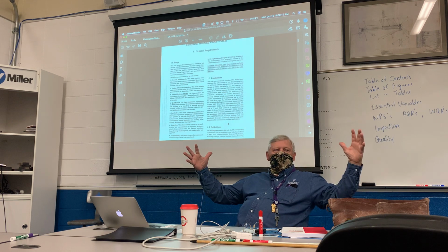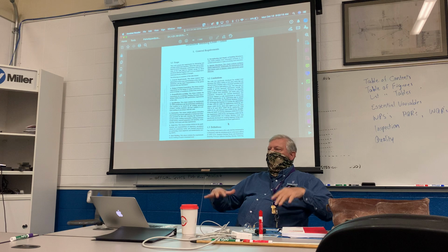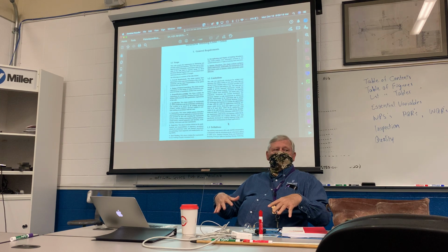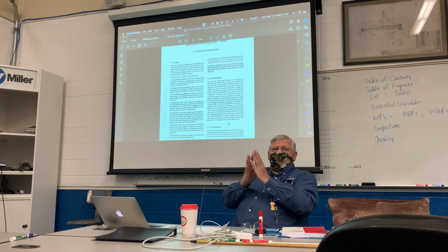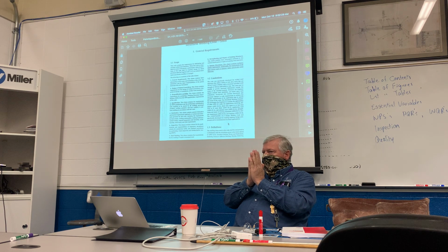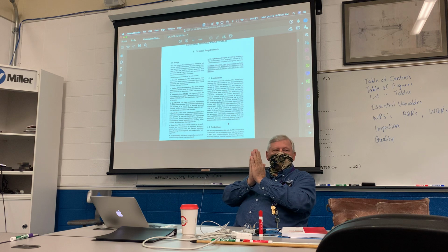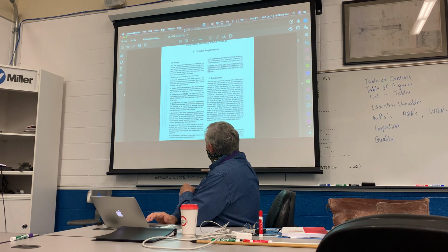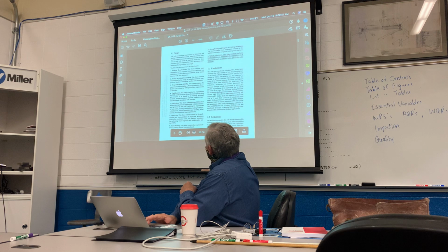And they keep the carbon content down low enough that you can actually weld on it. It's actually fairly low carbon steel. But you put that in concrete because concrete has very low ductility. So they put that in to keep the concrete rigid so that it doesn't move, so it won't crack. But there is a code for welding rebar. Okay.